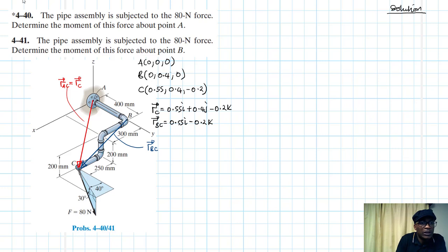Alright. Then what are the components of this particular force? Let's find it. So this force will have a component along this direction here. Here it will be mapped up like so. Okay, so we'll have a force in that direction. So we are mapping this force there like so. Alright, and this component is going to be equal to F cos 30,